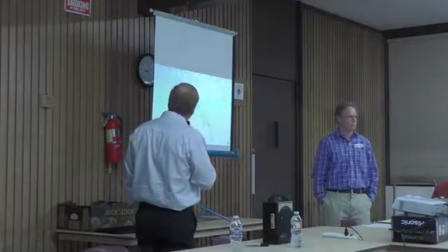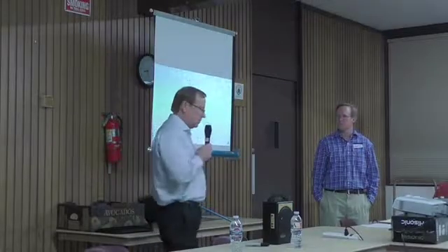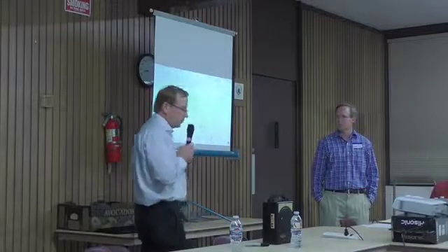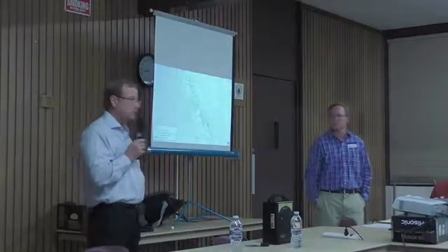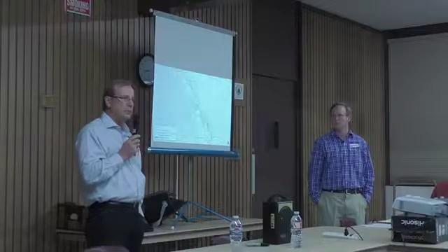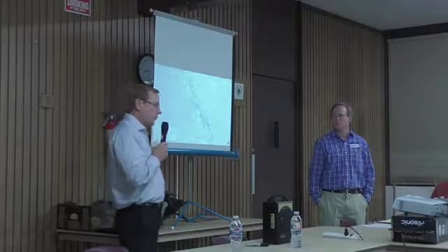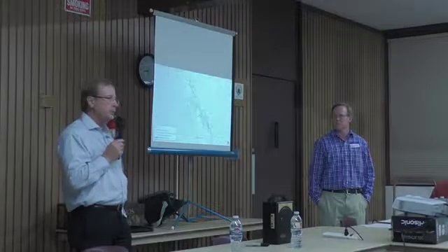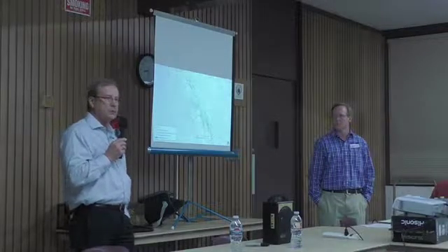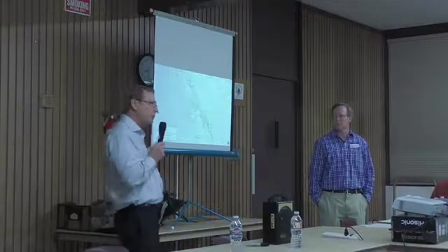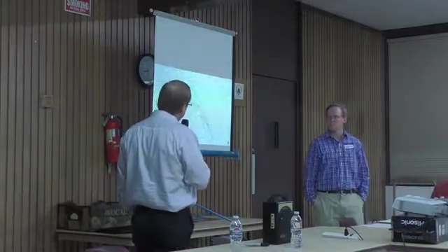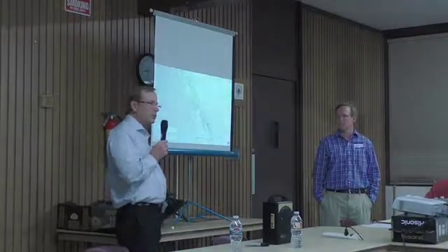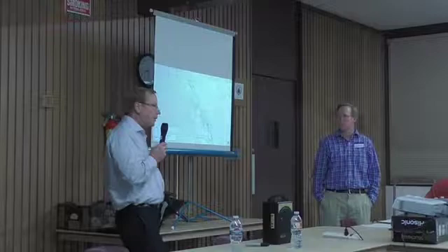As a result, what we looked at for water supply for the community, first and foremost, we had a hydrogeologist sub-consultant take a look at the valley in a holistic approach, reviewing literally more than 100 well completion logs for the general area so that we could get a better idea of where potentially the better producing wells occur within the valley.